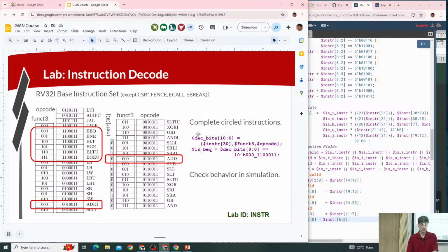We're going through the whole CPU core to implement the functionality that's needed to execute our test program. We're going to implement this subset core, see our program running. We'll go back later and add the other instructions back in and all the details. The instructions that we need for our test program are ADDI, ADD, and branch less than, I think. Since we're implementing that branch, we'll just go ahead and implement all the branches. So we'll do all the branches and ADDI.